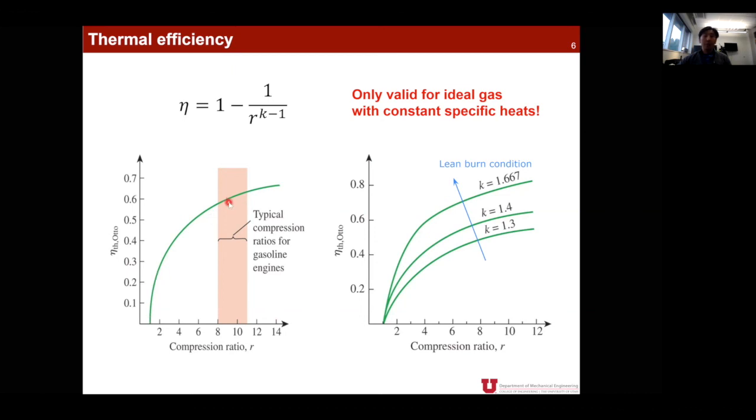But the problem here is that the gasoline engine is limited in terms of the compression ratio. As I said in the previous lecture, the compression ratio of a spark ignition engine is limited to around 8 to 11. So 11 is around the maximum value of compression ratio we can design for the gasoline engine. The question is, why? Why is the compression ratio for a spark ignition engine limited to around 11? Okay. Then we can find the reason in the next slide.